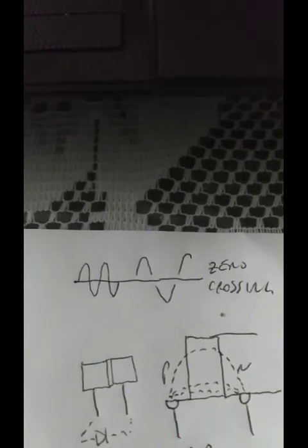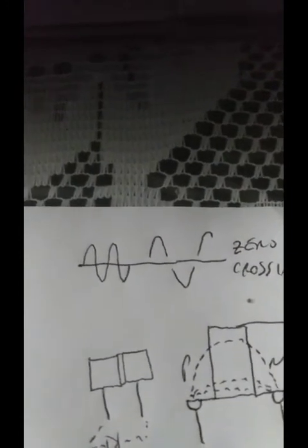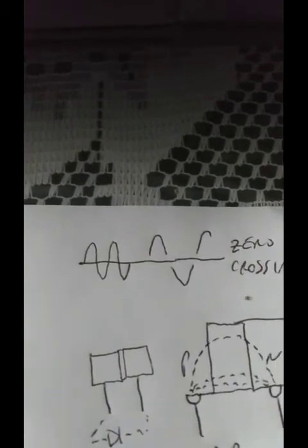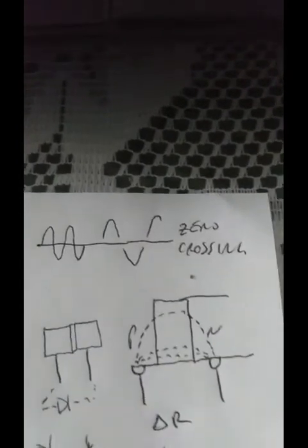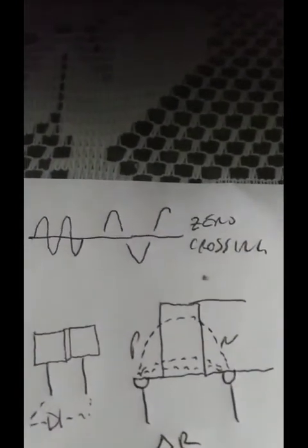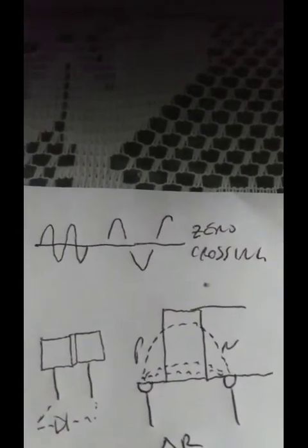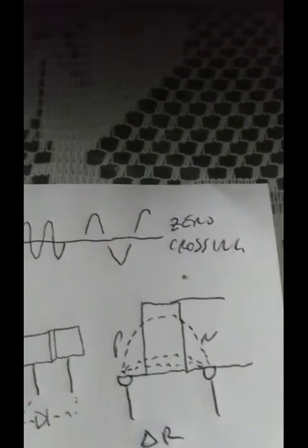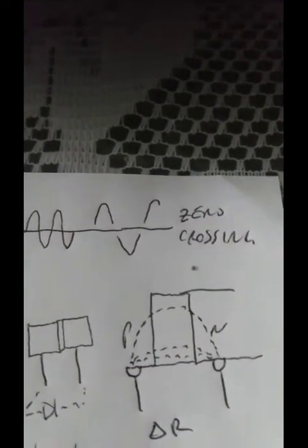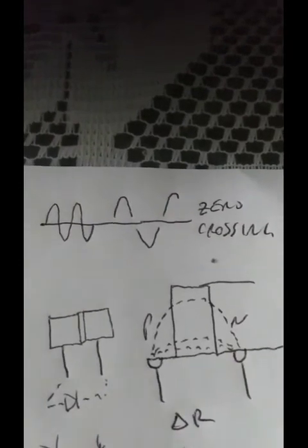The no conduction region is important because with a modulating signal that looks like the sine wave on the left, that is a continuous function. It starts at the zero line, goes up to maximum, back to zero, down to minimum, and back. What that no conduction region does is essentially blank out that signal at zero crossing. So there are gaps in it, and the higher that potential hill, the further up on that modulation envelope the modulation voltage will have to be to begin conduction and begin mixing.